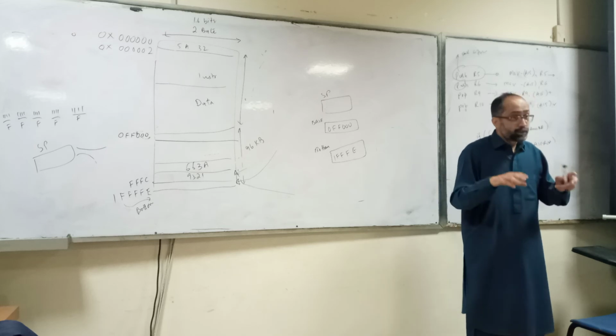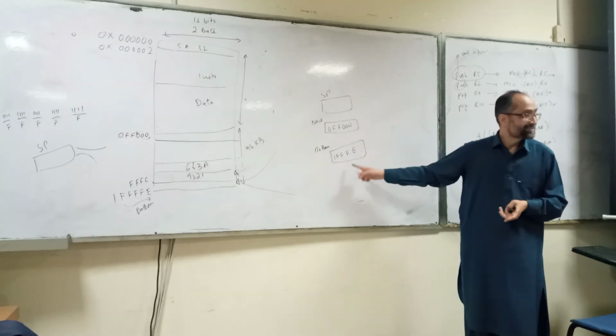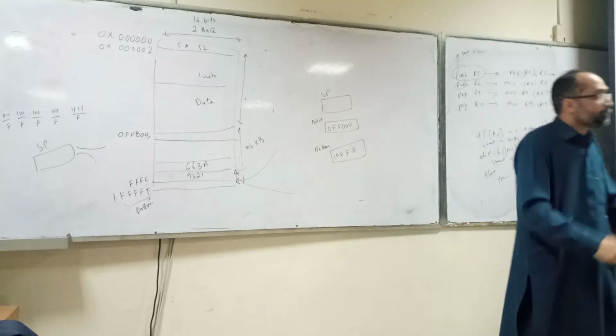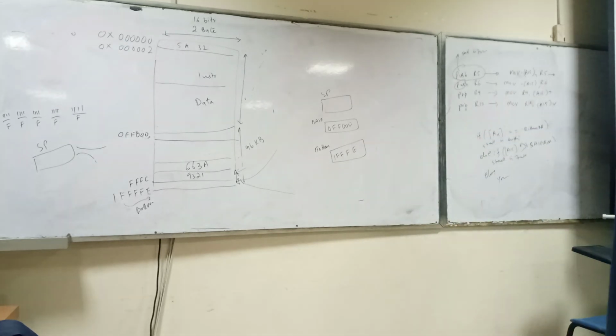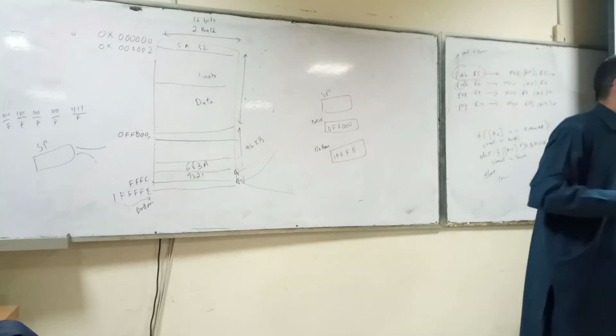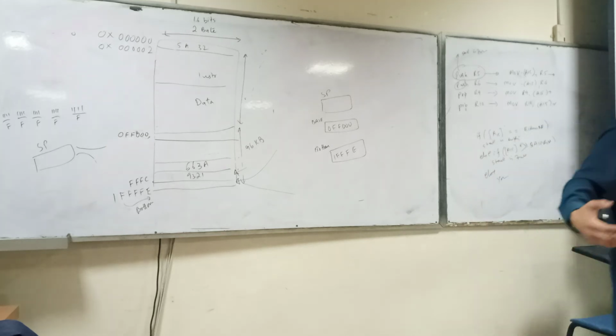Yes, system specific. So if you want to perform push and pop operations, and if the architecture supports this, you are reducing the code size. Why? Because if you are pushing, for each push you need 1 instruction. If you want to perform 1000 push operations, you need 1000 instructions unless it is in a loop. So you are increasing the code size.